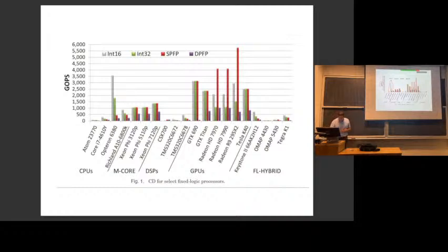So you see there's basically a 2x advantage of doing 16-bit operations. Why can they do more integer than floating point? Probably they built more integer units. That would be my guess. And then if we go into these many-core devices, which are targeted more at supercomputers, they basically focus their SIMD operations on single precision floating point. So that's why single precision floating point is the same as everything else. They just didn't bother to make 16-bit integer, et cetera, get more throughput in the SIMD units.